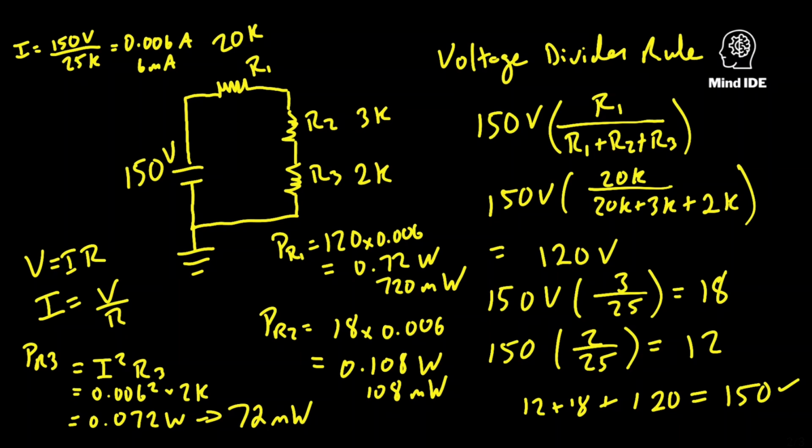You can do this voltage divider if you want, if you don't actually need the current. A quick voltage divider is really good if you don't really care what the current is and you just want to find the voltage drop across a particular resistance. So the only other thing I can say is just kind of what to think of. These descriptions aren't going to be exactly accurate, but they work if you're just starting out, and it's usually what they teach you when you first start out.